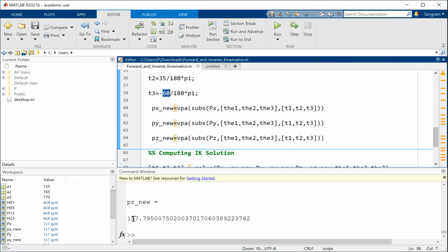3D printing. You have a geometry that needs to be 3D printed and you have this gantry. The gantry has certain joint values at a certain point in time. You have this CAD model, which specifies Px, Py, Pz at every layer, every location. For each Px, Py, Pz, I need to know what should be my J1, J2, J3. For my next Px, Py, Pz, what should be J1, J2, J3.